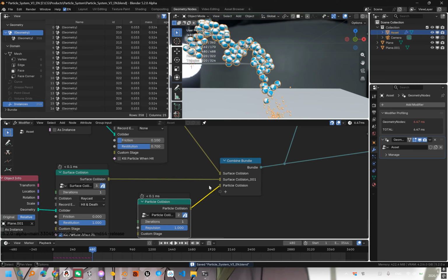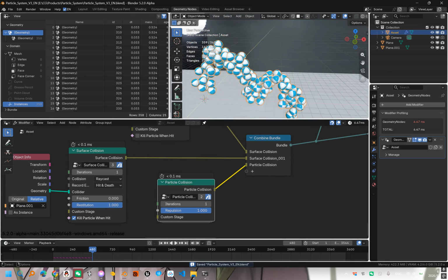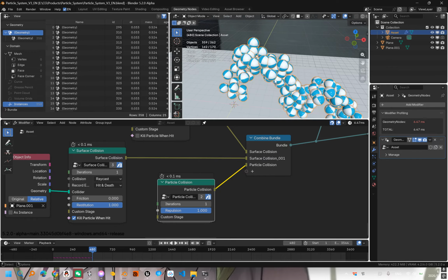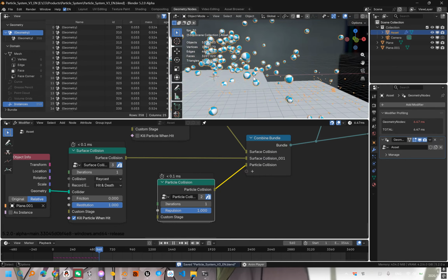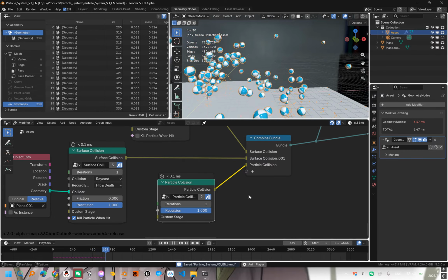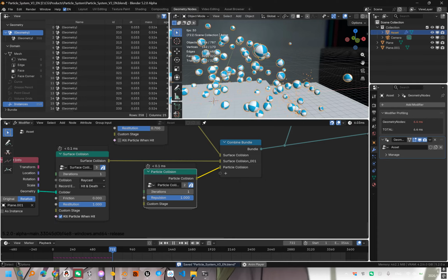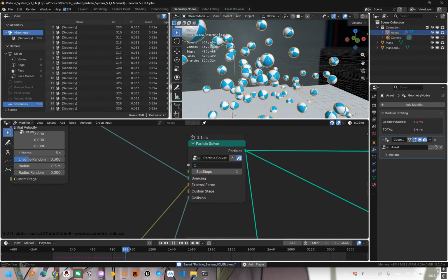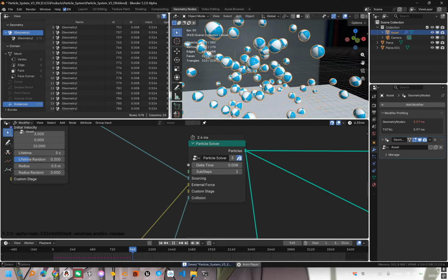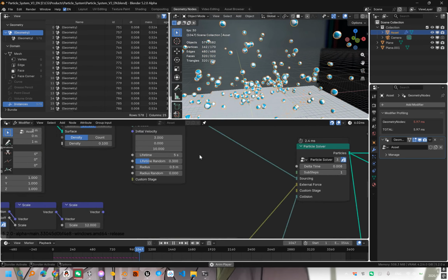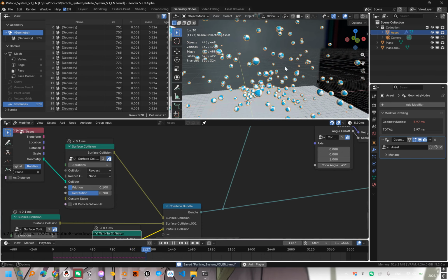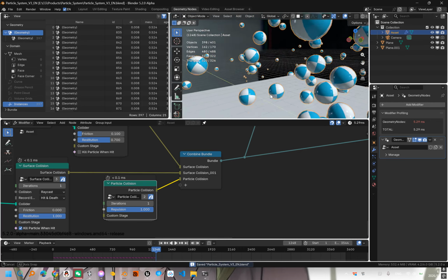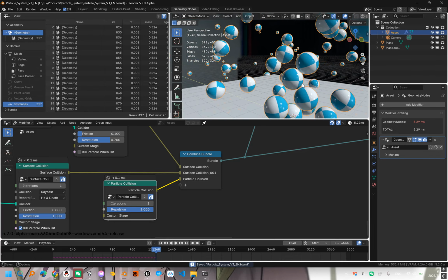We also have a particle collision here. The particle collision will push the particles away from each other to avoid particle self-intersection. As we can see, we have this particle self-collision, and this one actually depends on the delta time here. So if you make it smaller, you can see the particle collision is still pushing the particles away at the same speed, because this one gives you the natural behavior.